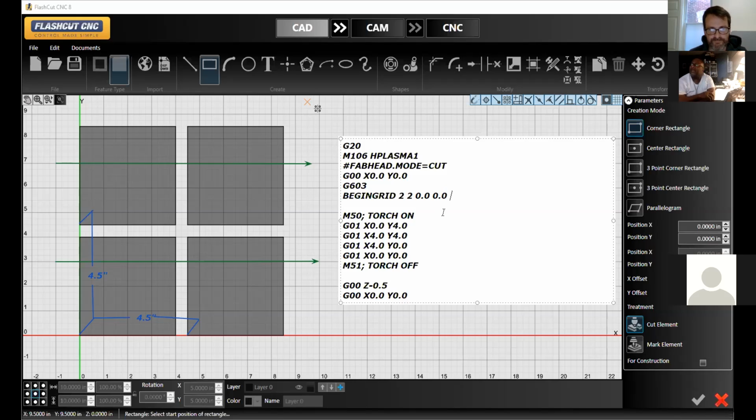I thought the next thing was a spacing, a half an inch. Well, we can set it, but the directions that I gave were, I messed up when I wrote the initial one. We can actually have it start anywhere. This portion is just the start position. So we could have it start at 5.5, or we could start at 8.5. This first command is only where we want the grid to begin.